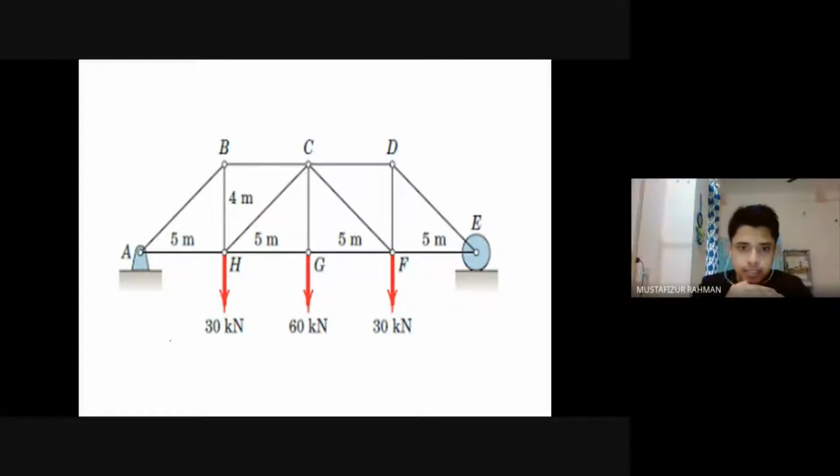If it is a roof system, then we will analyze the forces coming onto the truss system from the dead load of the roof, from the imposed load, if any, from the wind load, and other types of load, if any. By this time, I think we know the types of load. We discussed gravity loads in the direction of gravity: dead load, live load, imposed load. There may be other types like snow load. There may be horizontal loads, mainly earthquake load and wind load.